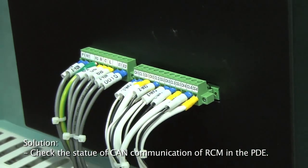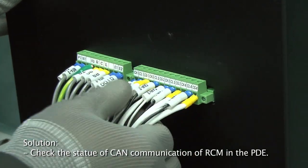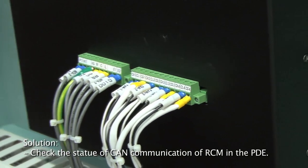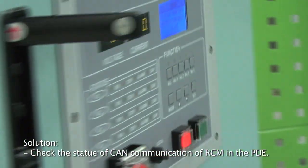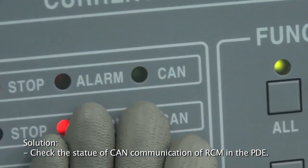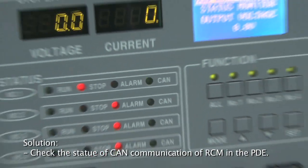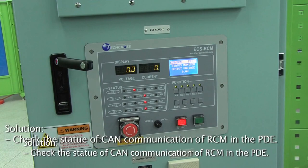CAN LED lamp, green light blinks every 1 or 2 seconds. Abnormal communication mode. CAN LED lamp, light stays either on or off. In case of communication failure, check the connections of RCM connector and cables. If cables are loose, connect them tightly again. If the same problem persists, please contact the manufacturer.